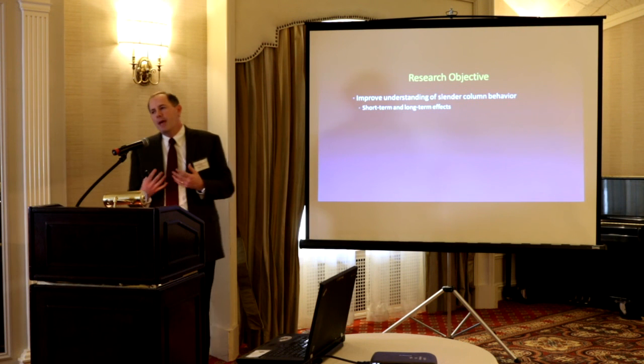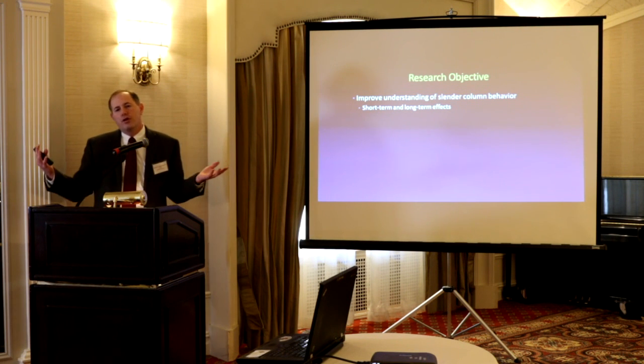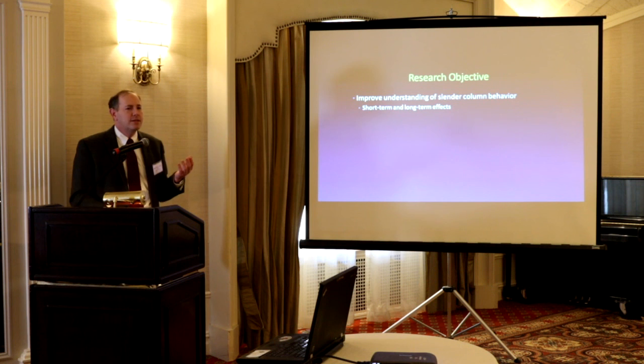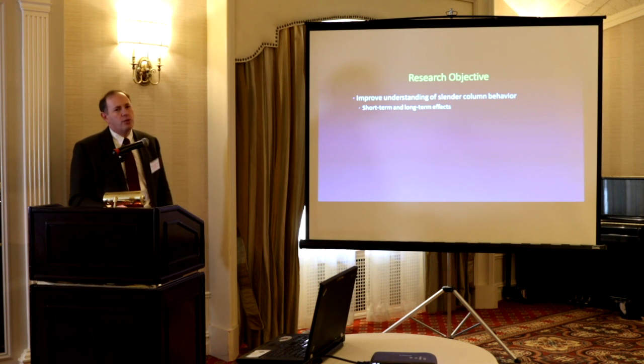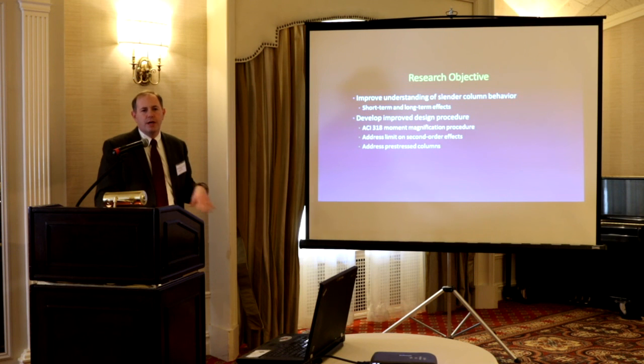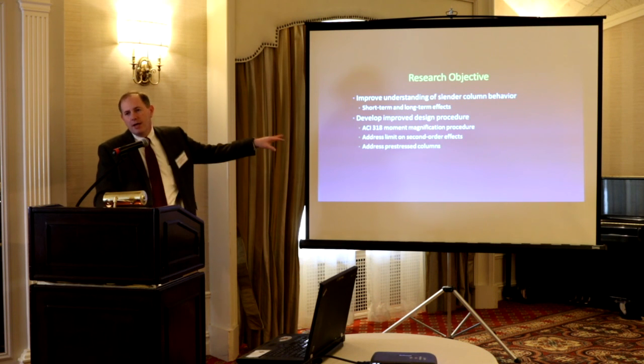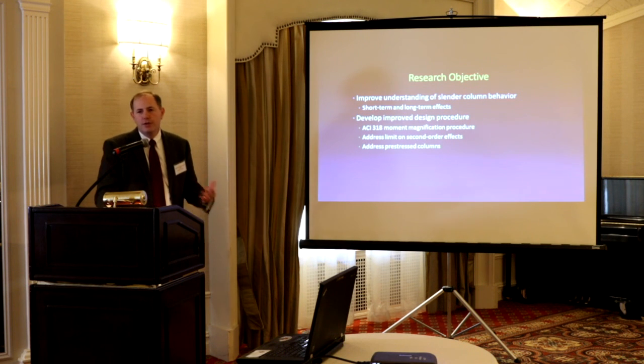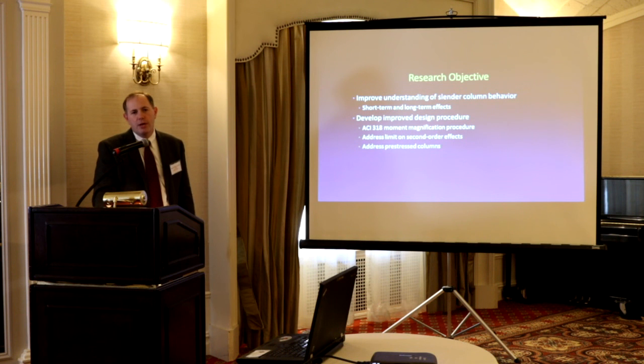One is to really improve the behavior understanding. No one had really looked at slender columns since that time back in the 70s. Looking at both short-term and long-term effects. And then we wanted to develop some maybe improved design procedures for the moment magnification procedure. So we're looking at the non-sway, because this is where we really need to have this benefit, and address this limit on second order. Do we need it? Do we not? And then, like I mentioned, for PCI, they were very interested in the pre-stress columns. I am not going to focus the talk today on the pre-stress, just because of the nature of the time here. We'll focus on the